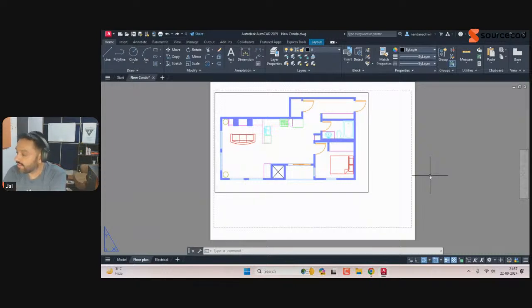Okay. Then we have another question from Edward. Is there a way to change the default paper layout setting? So any layout created in the future use desired default settings. You can just copy your existing layout. So rather than clicking on the plus icon, you can just make a copy of your existing layout, rename it, and then it's just going to use the same settings.